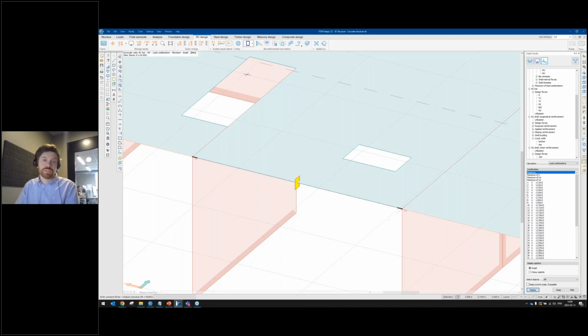Well, first of all, you can always find the settings for the check under the cogwheel and under the calculation parameters. So the first settings found under the configure RC design, the cogwheel here, they will affect all different design situations, regardless if it's a shell or a bar or a punching region or whatever it may be. And in this case, it's relating to how to handle the second order effects and also which load combination should be used for the crack width calculation. And also there's an option to calculate reopening of cracks. So otherwise the crack limit will be FCTM, which is the tensile strength of the concrete.